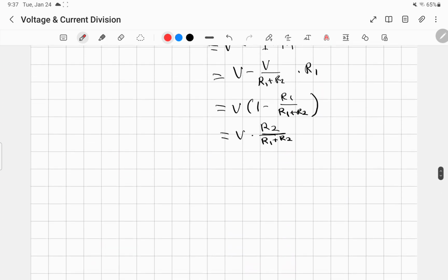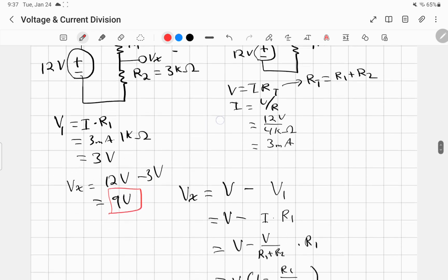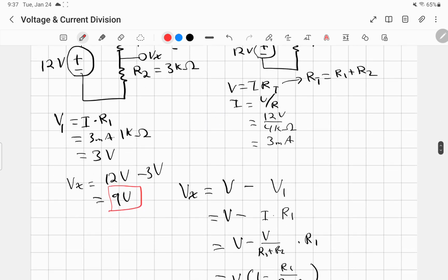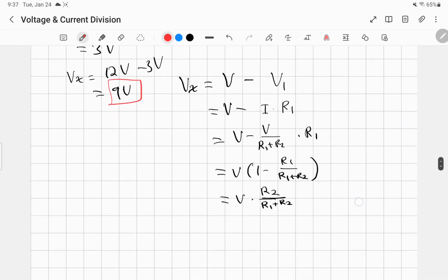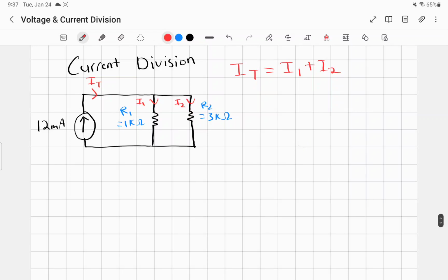And similarly up here, Kirchhoff's voltage law, all the voltage through one loop is going to add up to 0. Okay, so that means a 12-volt voltage increase is going to be equal to the sum of the voltage drops through these two resistors. That's where I got that from. Just to be perfectly clear, bringing this back to KVL and KCL, which are very important for you guys to really understand and know.